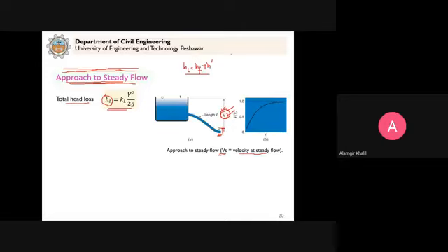You see, we write down HF. How do we write down HF? This will be equal to f L by D into V square by 2g. So this can be written as K. So we have H is equal to K V square. So this is not just minor loss, remember that, because only minor loss is expressed as velocity head with a loss coefficient.